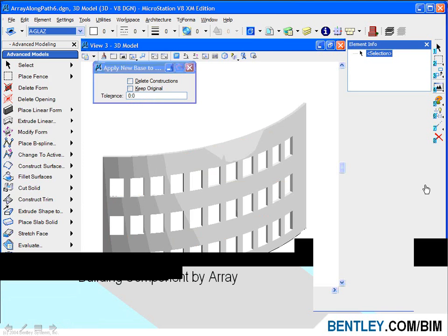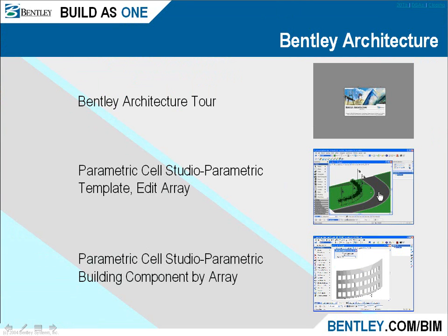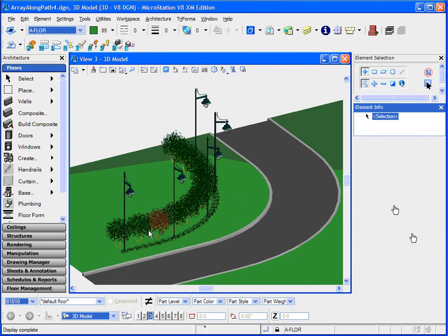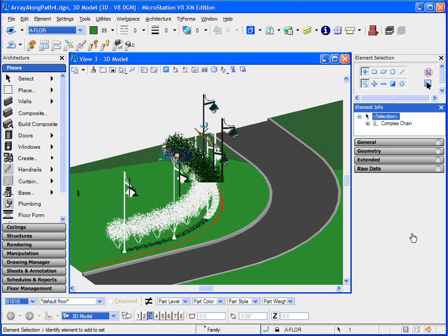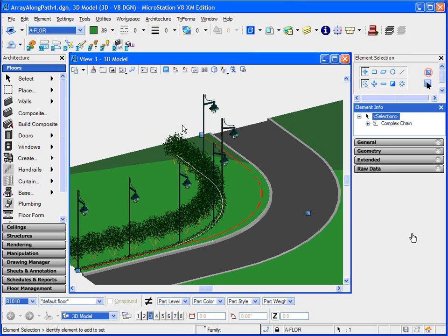Like that. Here's another type of array. Who asked that question? Oh, this was Al. Al, okay, look right there. Edit template. The element array tool that you're looking at right here is from the element template along the top left-hand corner of my screen. That little pull down that you see up there in the upper left-hand corner next to A floor, right there is where the element templates are created.